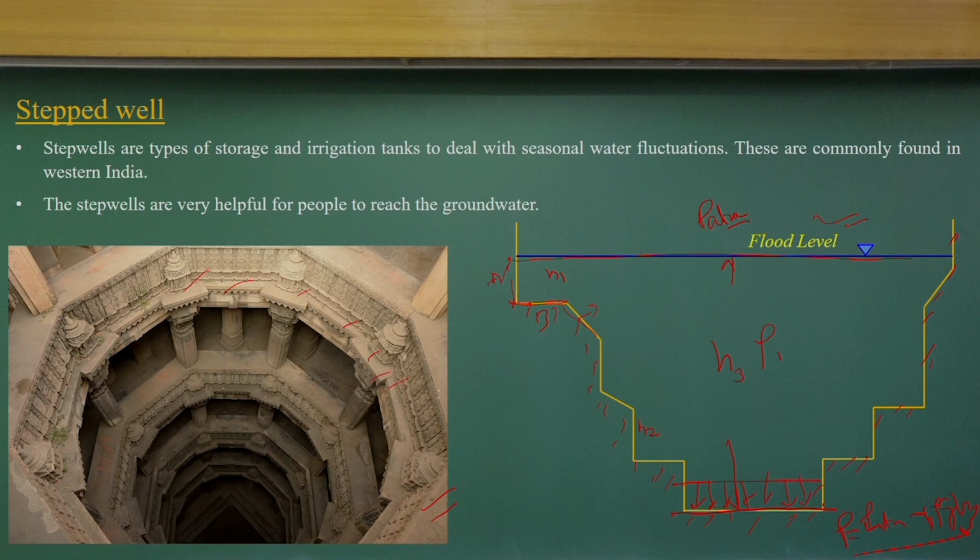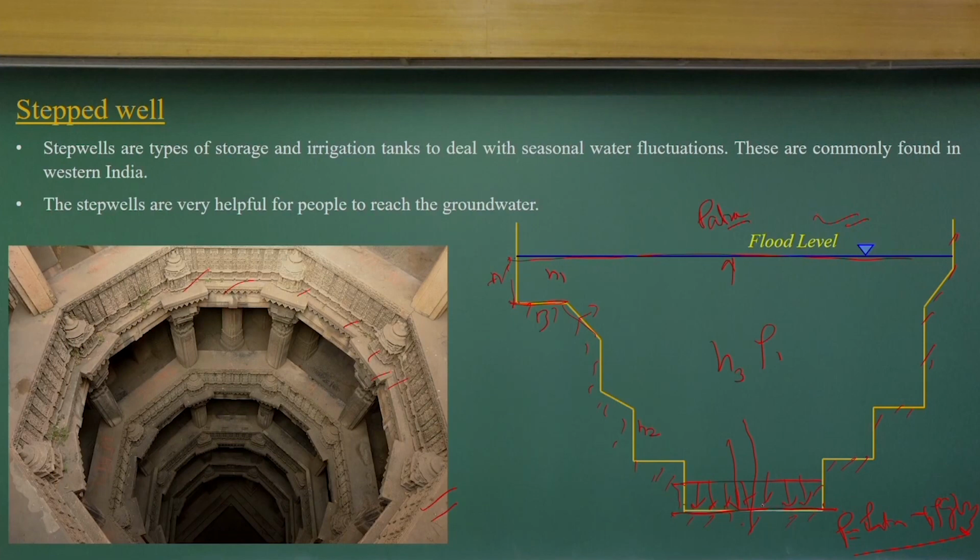As it is a horizontal surface, you will have a uniform pressure distribution, so the maximum force will act at the centroid of this surface. As the pressure distribution is uniform, the center of pressure, where the pressure force is acting, will match the centroid of this surface. The surface can be circular or elliptical in shape, but that is what will act on it. So, you have the pressures of that.